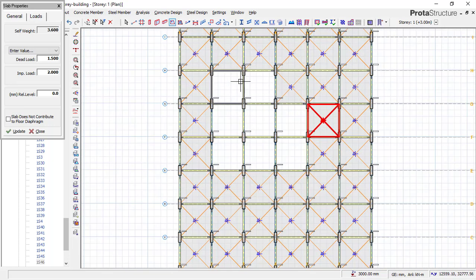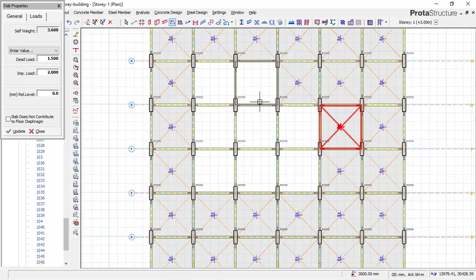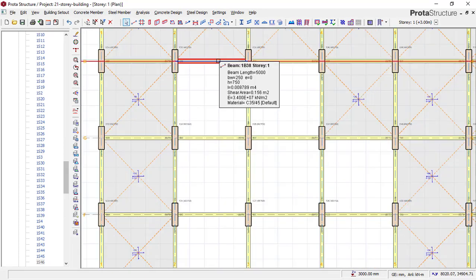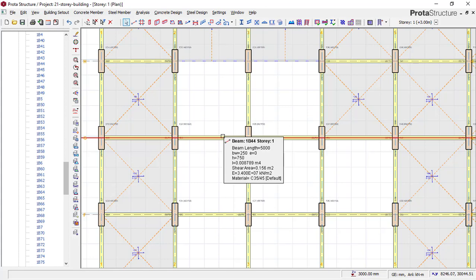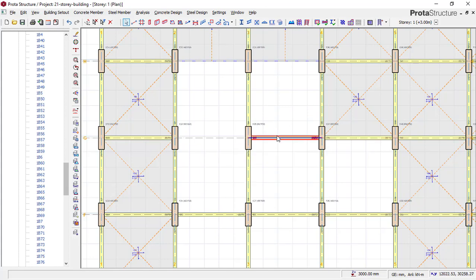Okay, now at this point we have our lift. We have a shear wall, a lift wall at this area. So we'll quickly introduce our lift before we begin our slab again. At this area, let us insert a lift, a shear wall. To insert a lift, we have to remove these beams on this area, the shear wall.